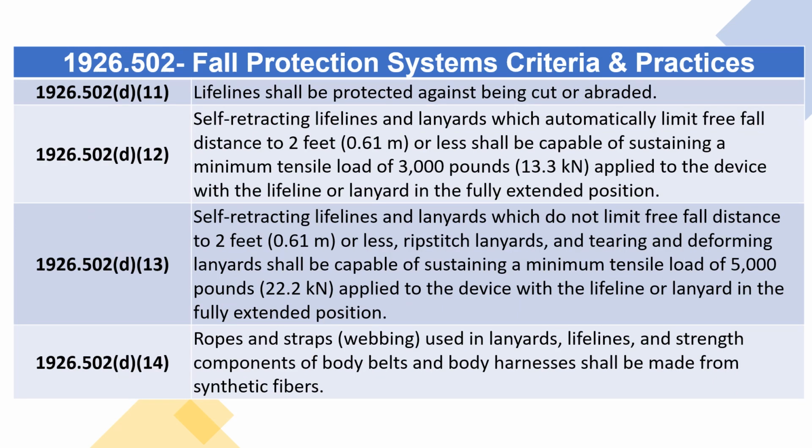1926.502 D11: Lifelines shall be protected against being cut or abraded. 1926.502 D12: Self-retracting lifelines and lanyards which automatically limit free fall distance to 2 feet (0.61 meters) or less shall be capable of sustaining a minimum tensile load of 3,000 pounds (13.3 kN), applied to the device with the lifeline or lanyard in the fully extended position.